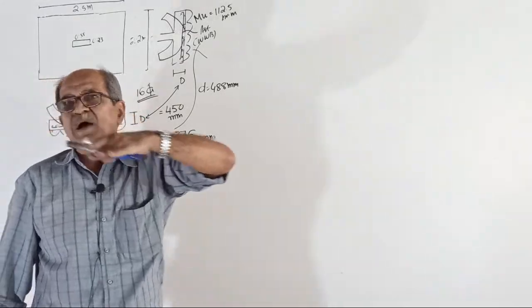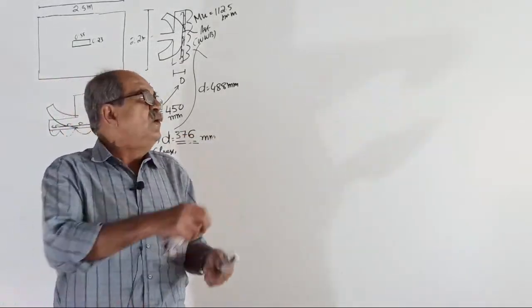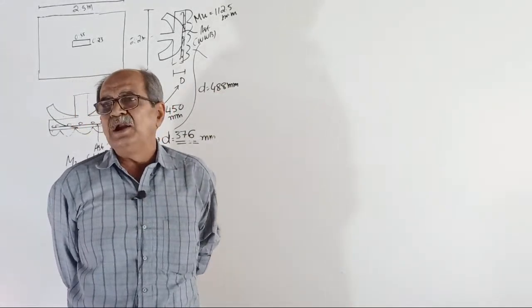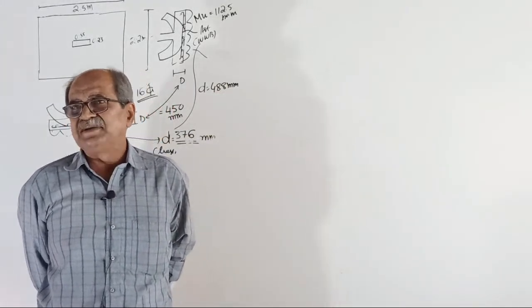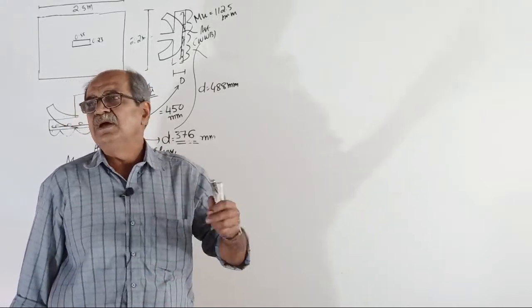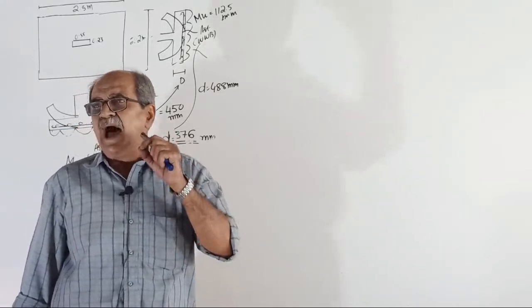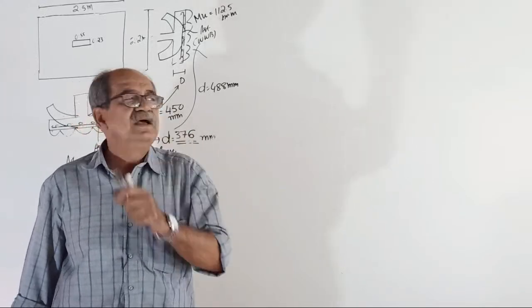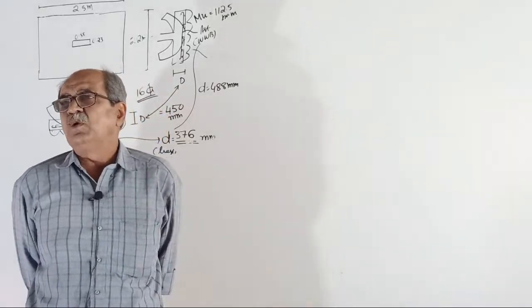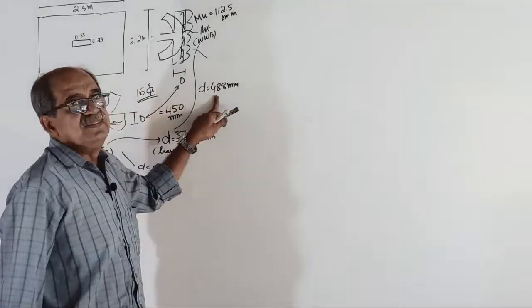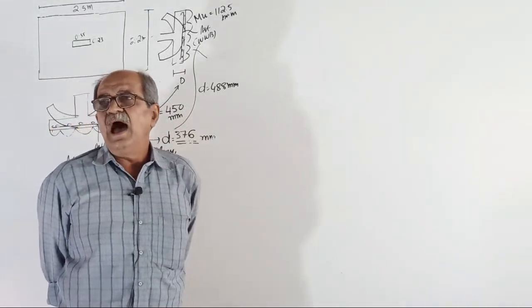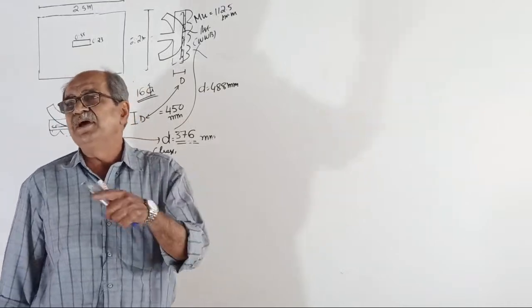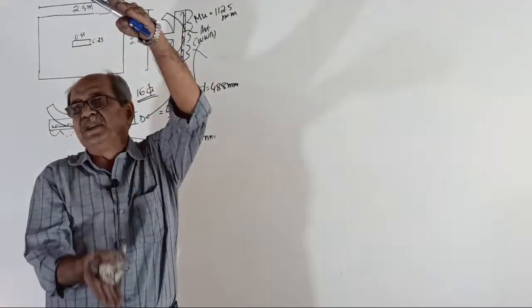We considered lengthwise bending and found the BM. We considered widthwise bending and found the BM. Both of them are due to working load. Then we factored it and got the factored BM. Then we equated the factored BM to the maximum factored BM of the limit state and found the effective depth D required. Then we added cover, half diameter and one full diameter, considered that least D, and got the overall depth required.